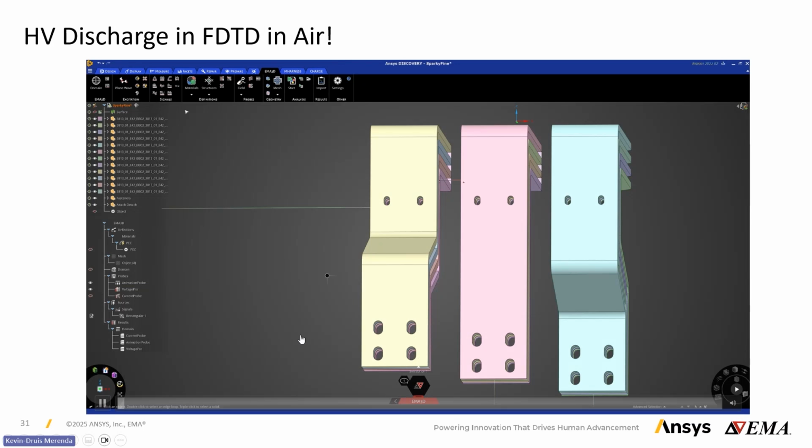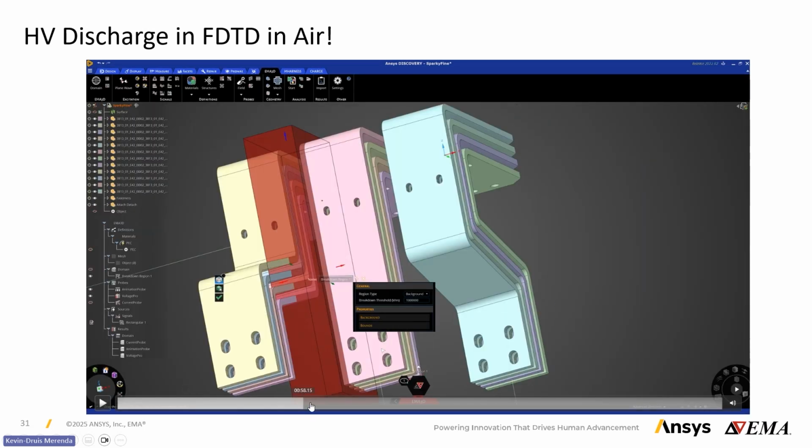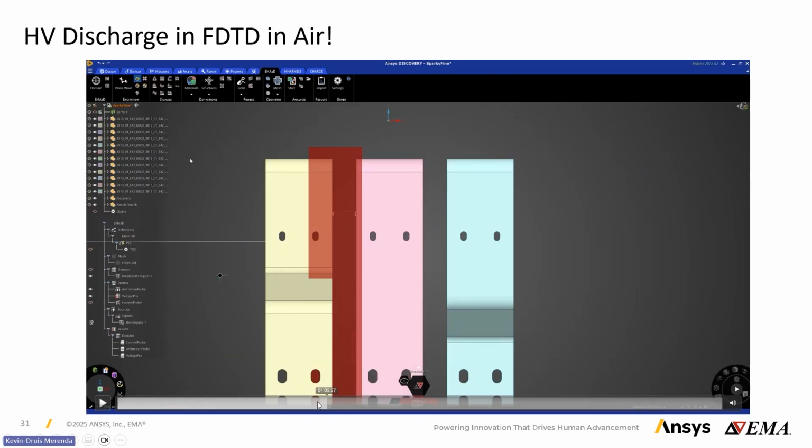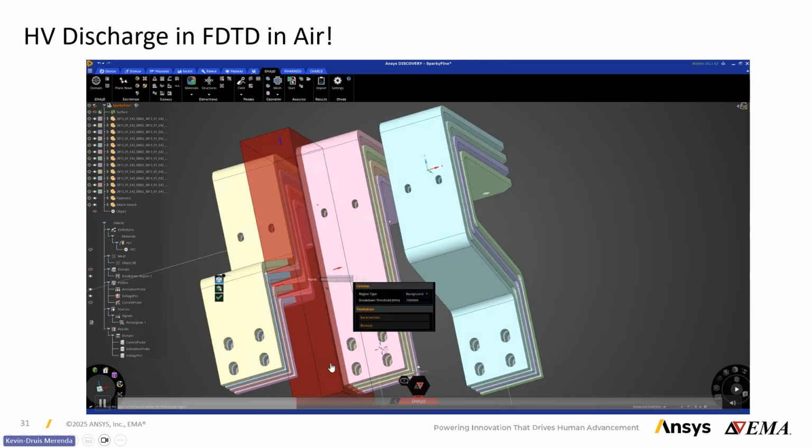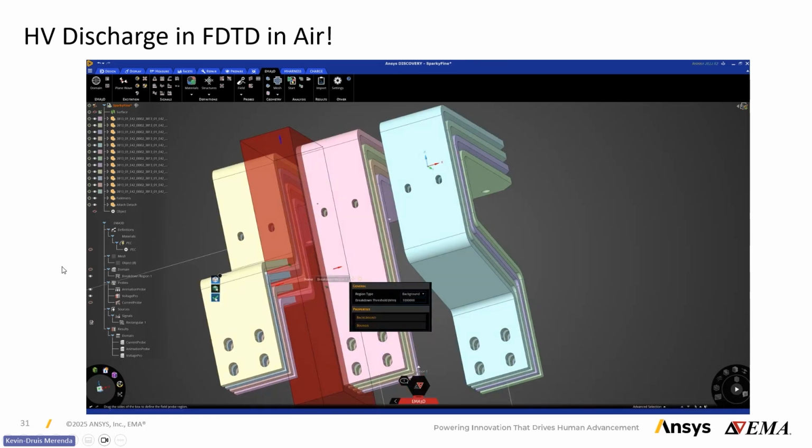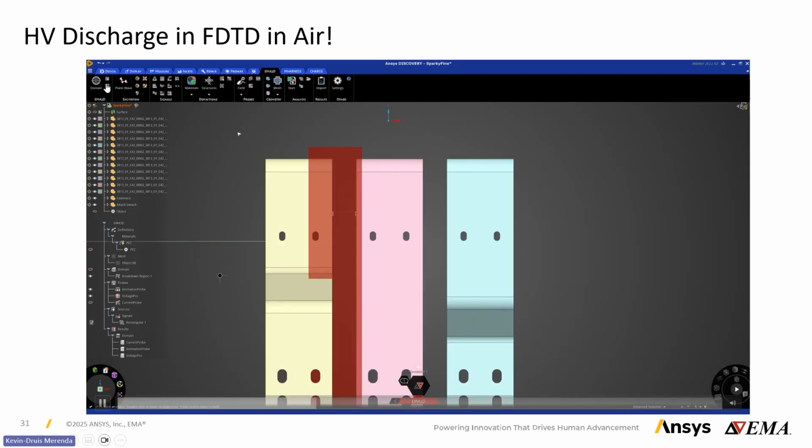So in the FDTD, things are pretty easy to set up. The air breakdown region is going to be just, in terms of inputs, the air density and the humidity, and you can actually click a sub-region of the space that you want to model, which we call the air breakdown region, and you'll find it in the EMA3D section near the domain.